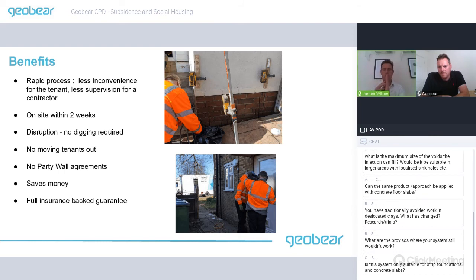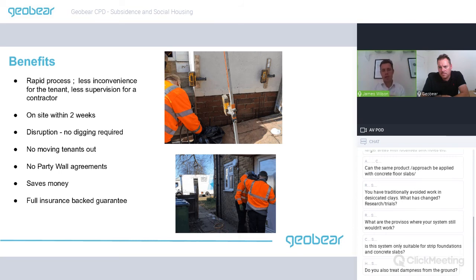So underneath the soil, you go from underpin to soil, and that's what's called a hard spot. You can get differential movement at the point where you stop that underpinning. But because our resin dissipates in the soil more gradually, you don't get that hard spot, so you wouldn't expect differential movement.